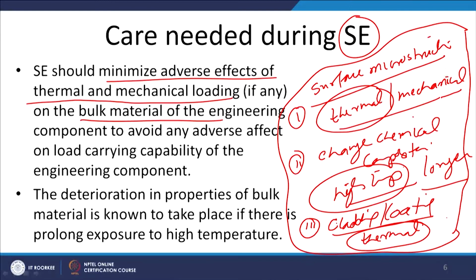The bulk material properties matter because the components are designed in such a way that the bulk material will carry the required load during service and perform the function, and functionality for a longer period will be facilitated by the improved surface properties of the component. So, the bulk material properties should not be degraded due to the mechanical or thermal loading of the component during the surface engineering, otherwise its load carrying capacity will be adversely affected.